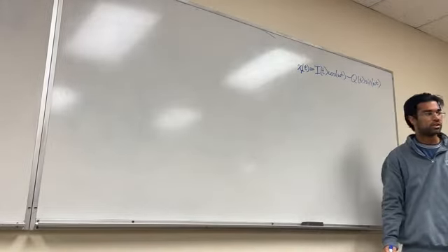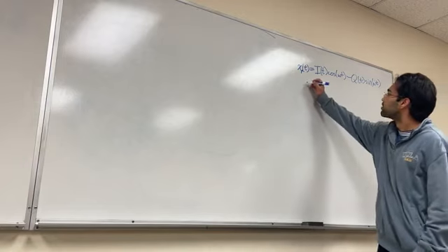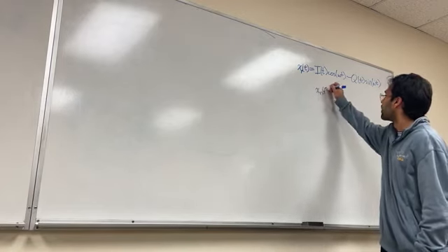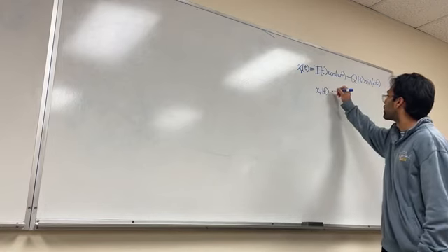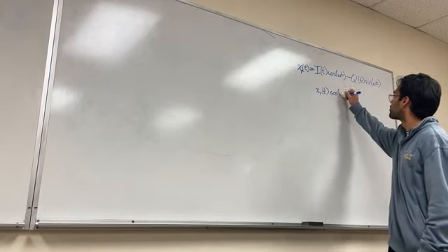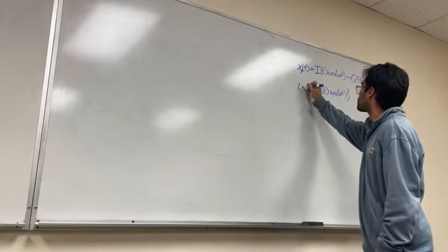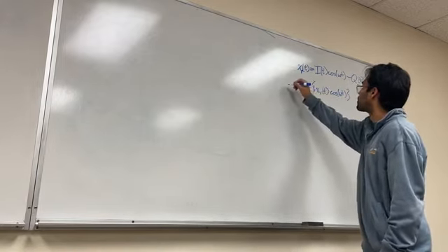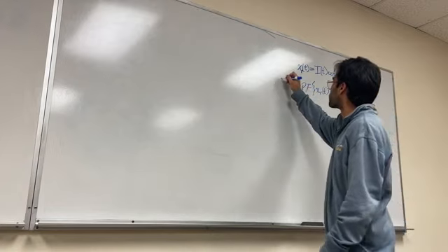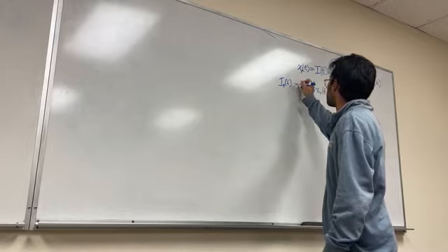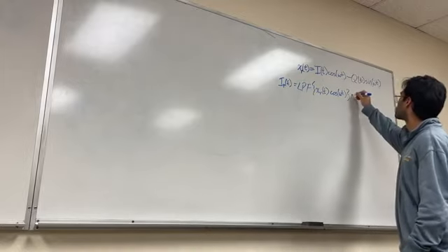And to demodulate it, what we do is we take this x of t and we multiply it by a cosine of t and take a low-pass filter to hopefully recover the in-phase component again, or do times 2.